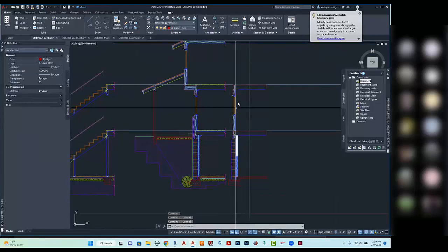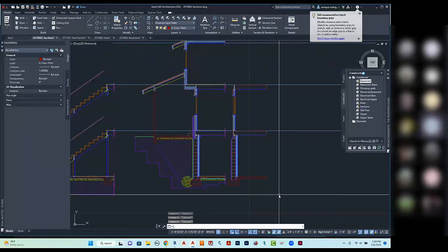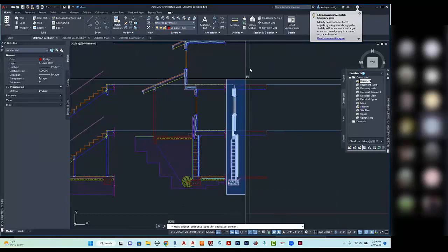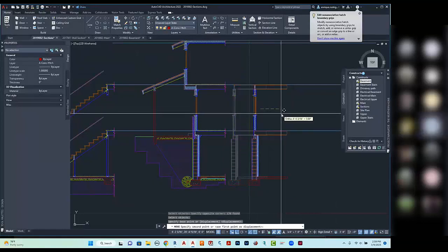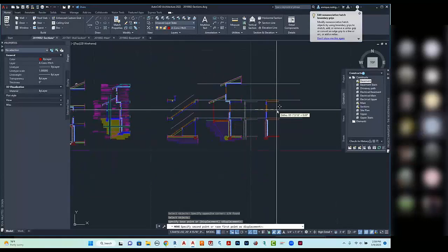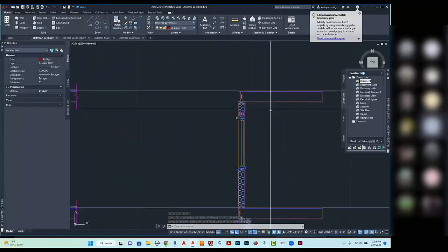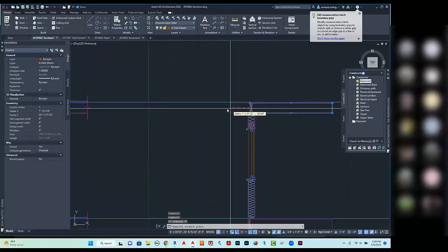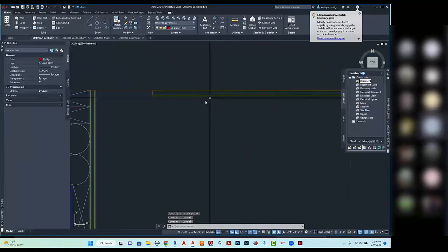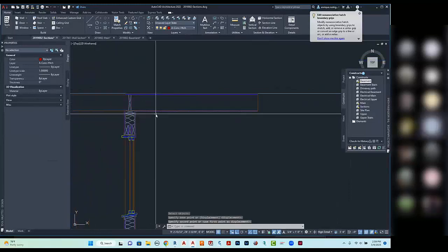Now notice, one of the things that happened here is I started my section way too close to here. So all I need to do is grab everything that I drew so far, and I'm just going to shift it over, give myself a little bit more room. Eventually, I'm going to want to give it enough room to be able to draw all of this in it. So I just shifted it sufficiently over. I'm going to go ahead and take my joist and stretch it out at distance. Use a stretch command, grab the drywall, and shift that over to there.